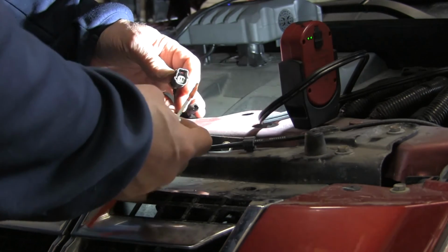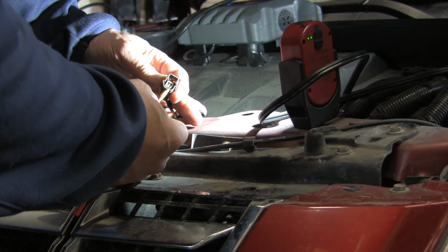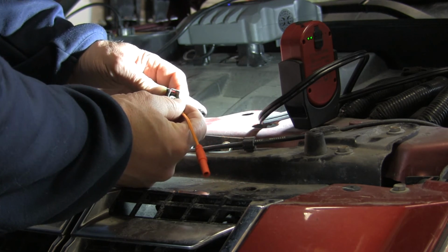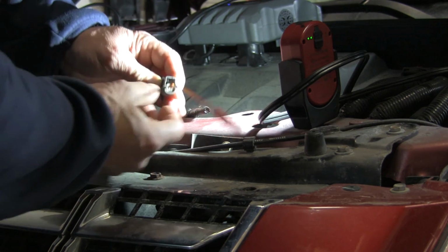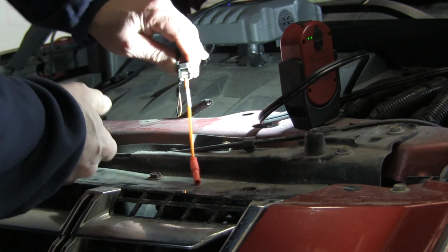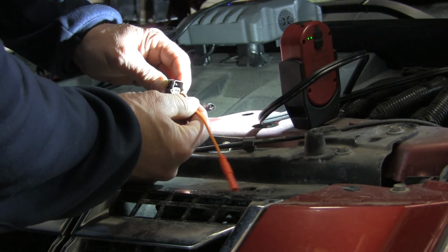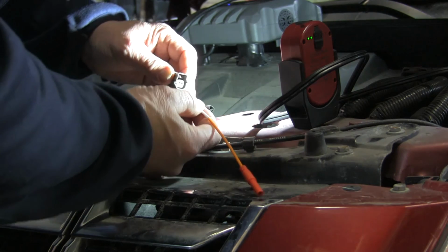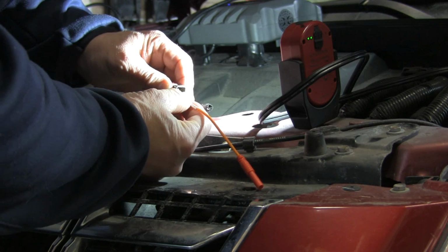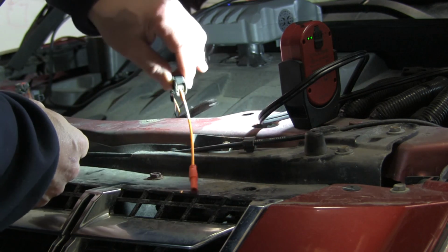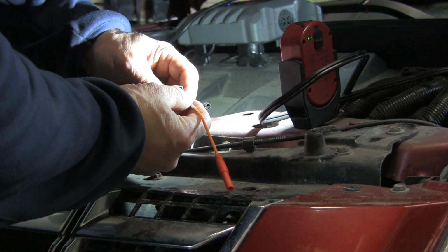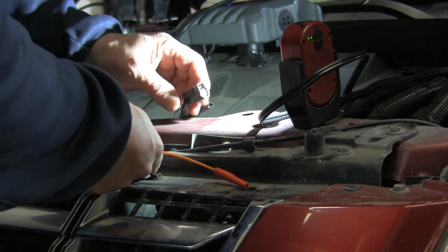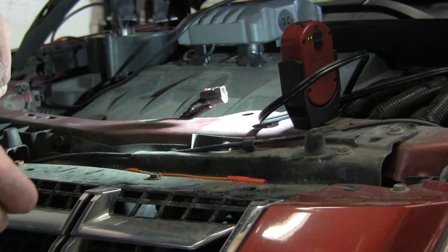So what we're doing here is we're testing the tension on these pins. Our testing with the scope showed us that we have changing voltage here but no current. That pin's pretty good. That pin, I don't know if you can see it or not, there is no tension at all on this pin. Won't even hold my test pin in place. So it looks like we've got a spread pin at least in this connector. So I'm going to have to take this connector apart and see if I can find another terminal for it, or maybe squeeze that one down.